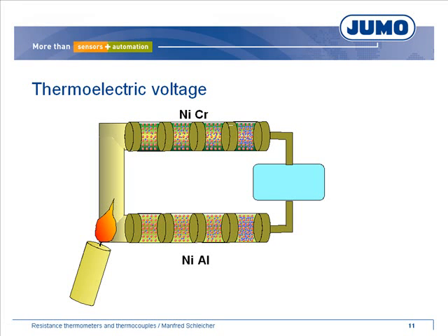Different materials cause a different potential shift. The thermoelectric voltage depends basically on the conductivity of the material. In the example, nickel chrome and nickel aluminium are used for the limbs. The potential shift of the materials is different. The cold end of the nickel aluminium wire is more overloaded by the electrons than the cold end of the nickel chrome wire. The electrons in the nickel aluminium wire can move 4 times faster than the electrons in the nickel chrome wire.